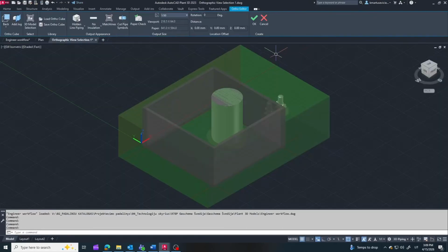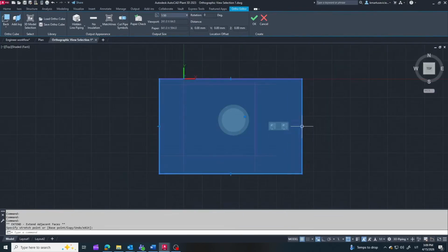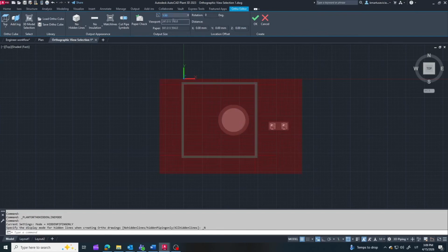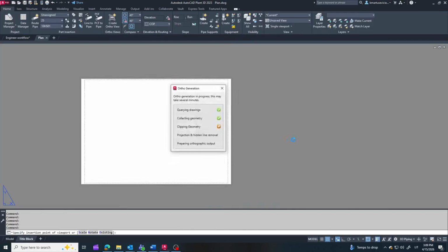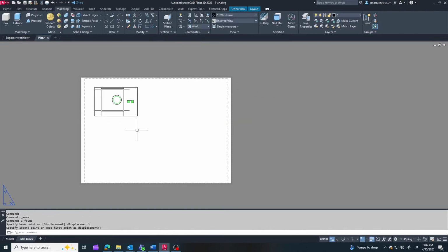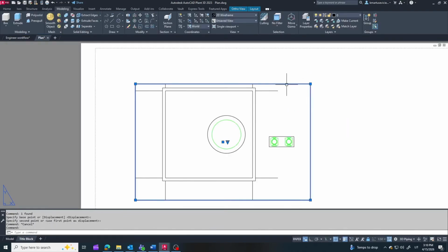With one general arrangement drawing, you can actually do two things. First, send it to the client for confirmation that the equipment positions are correct. Second, use the same drawing to create tasks for other disciplines like construction, electrical, and automation.